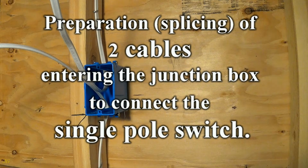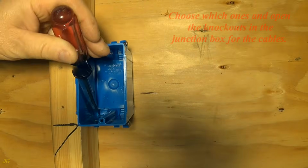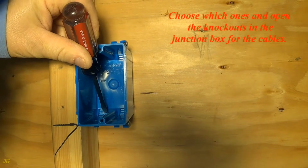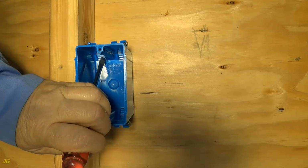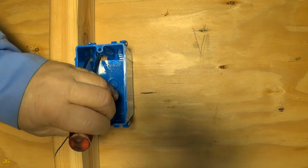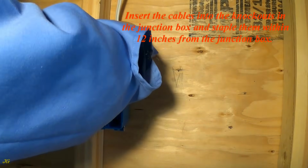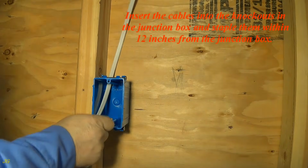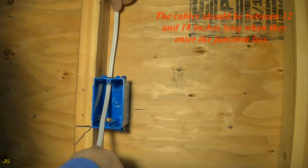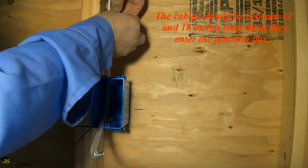Preparation, splicing, of 2 cables entering the junction box to connect the single pole switch. Choose which ones and open the knockouts in the junction box for the cables. Insert the cables into the knockouts in the junction box and staple them within 12 inches from the junction box. The cables should be between 12 and 18 inches long when they enter the junction box.